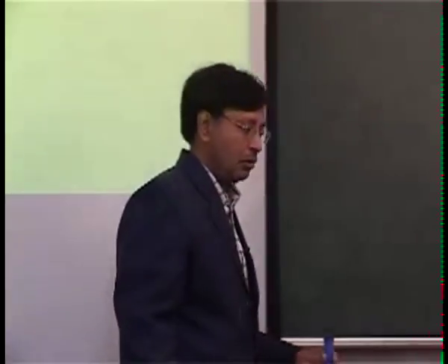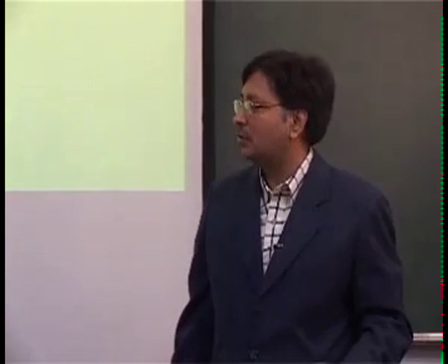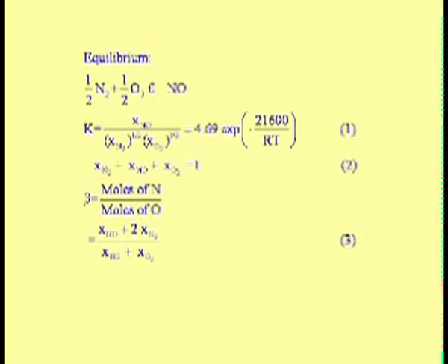You should try not to give too much excess air, and you should also try to keep the temperatures from going very high if you want to really control the NOx. Okay, and that's what is said here.